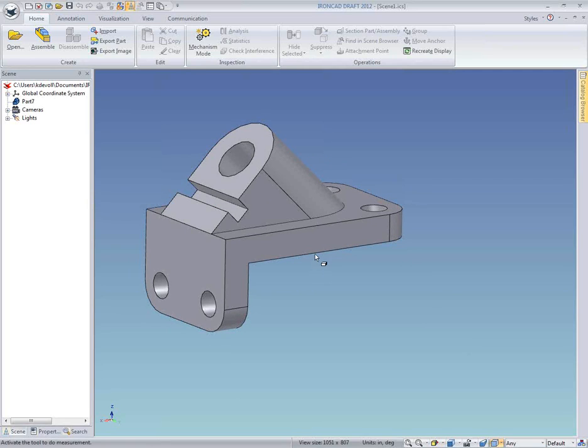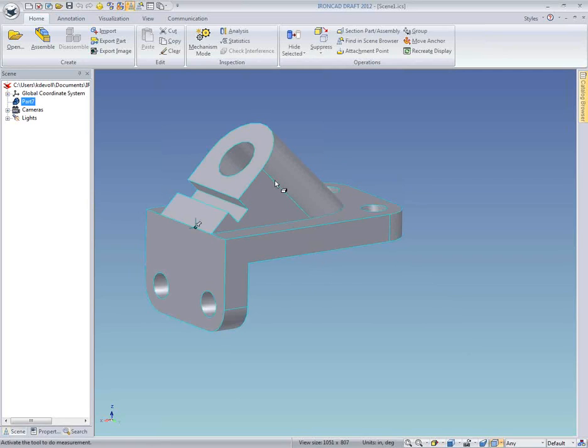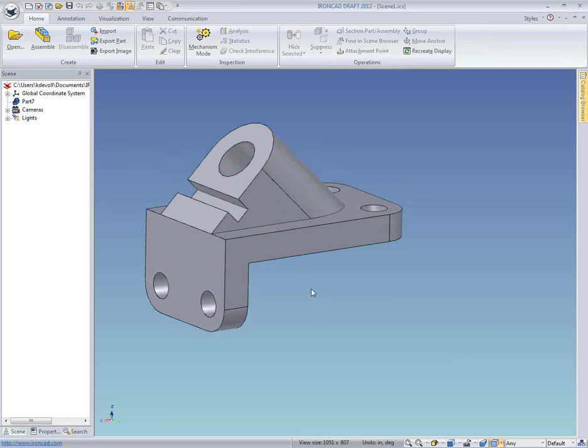And so yeah, the concept of Draft is you can bring everything in and move it around, but you can't edit the geometry itself. I can't change the size of anything. I can't move faces. Can't edit any IntelliShapes. So that's the limitation. That's usually good if you're sending somebody a finished part to a drafter, right? Yeah, it's good. You don't want the drafter changing the model.